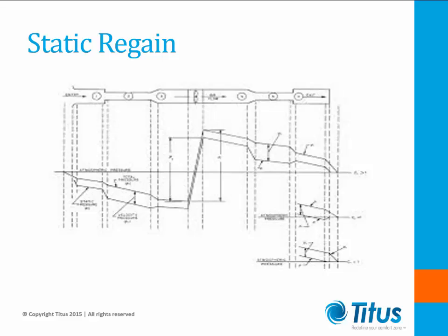Regain is regularly used, though, in risers, as the higher velocities allowed inside enclosed chases have adequate energy to be worth the duct cost. The enclosures help to maintain acoustic requirements and keep sound generation from reaching the occupants. Industrial installations generally do not have as stringent of sound requirements. This allows for the use of the higher duct velocities that make static regain design method the choice.